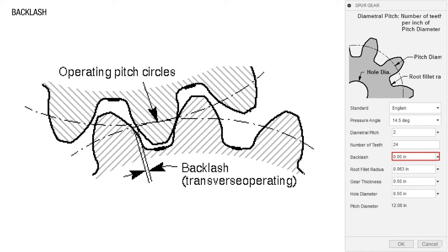But if you're carving these out of wood by hand, then you're going to have to allow more clearance around the teeth because your method of manufacturing is less accurate and it has larger tolerances. For that reason, your backlash is going to be larger than if you created it in a more accurate process. So the backlash in a perfect world is 0.